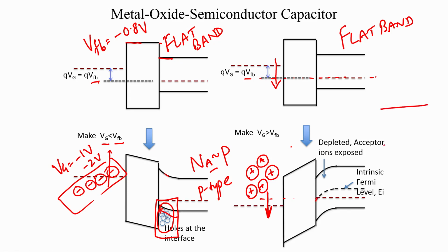So, you have the semiconductor, it initially had an intrinsic Fermi level position, and then after doping we shifted the Fermi level to a more p type semiconductor, and we are using the p type to create your MOS capacitor. But having said that, I have just indicated the intrinsic Fermi level. So, this is the Fermi level after doping and this is the aligned Fermi level, and we have also indicated the intrinsic Fermi level here.